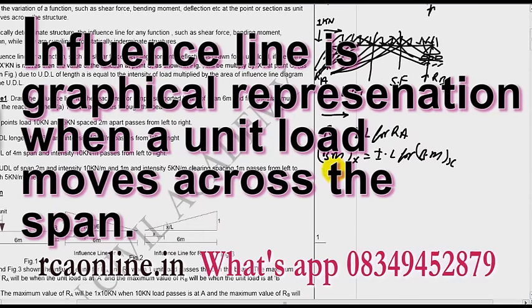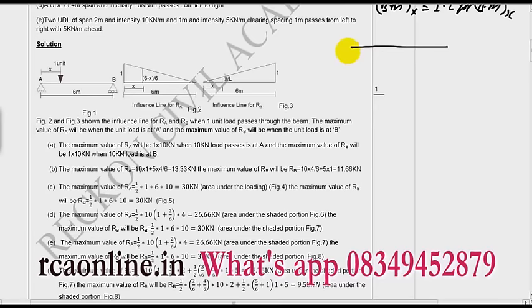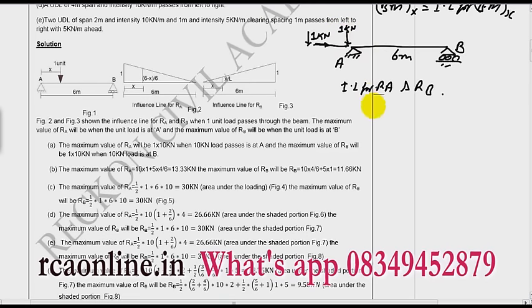I will make you understand this by a very simple example. Let us take a beam of 6 meter span, and a load of 1 kilonewton is moving from left to right. We want to find the influence line for RA and RB. So we will see that when the 1 kilonewton load is here, RA is 0 and RB is also 0.